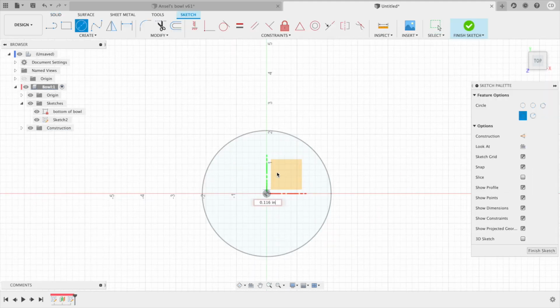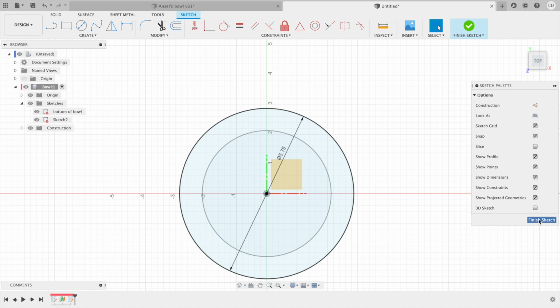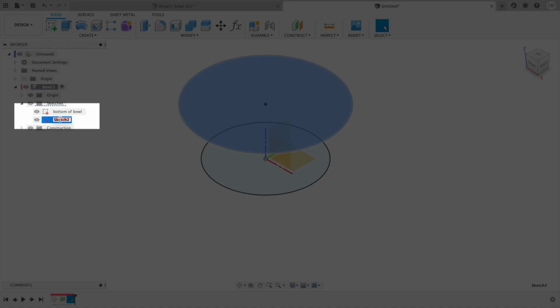So here I want to create a sketch for the rough dimension of the top of the bowl. So I create another circle, and I just hit C, the shortcut, but you could also select the icon. I select the center of the axis and create a circle with about 5 3/4 inches in diameter. As usual, I rename the sketch so that I have good organization.